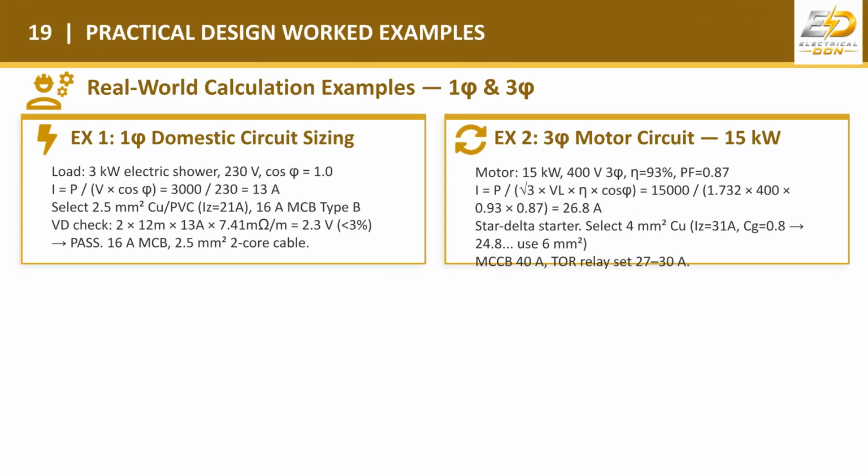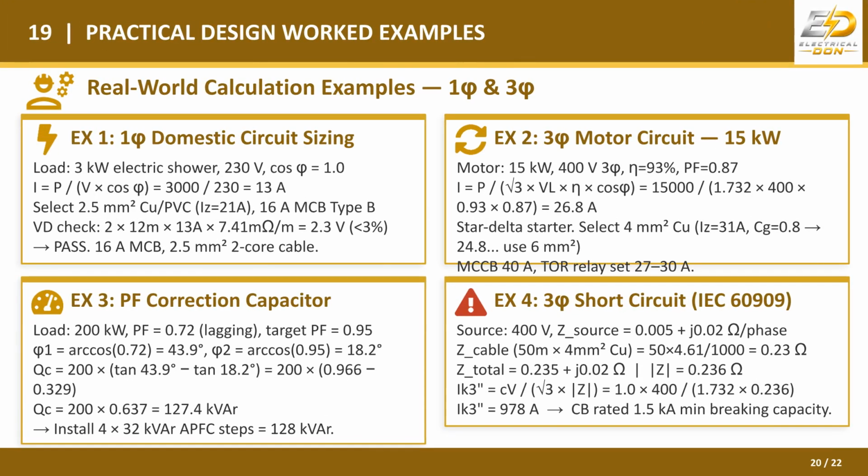We reviewed practical design examples, including single-phase circuit sizing for a 3 kilowatt shower and a three-phase motor circuit for a 15 kilowatt motor. Calculations covered current, cable selection, and voltage drop checks. We also examined power factor correction and short-circuit current calculation.